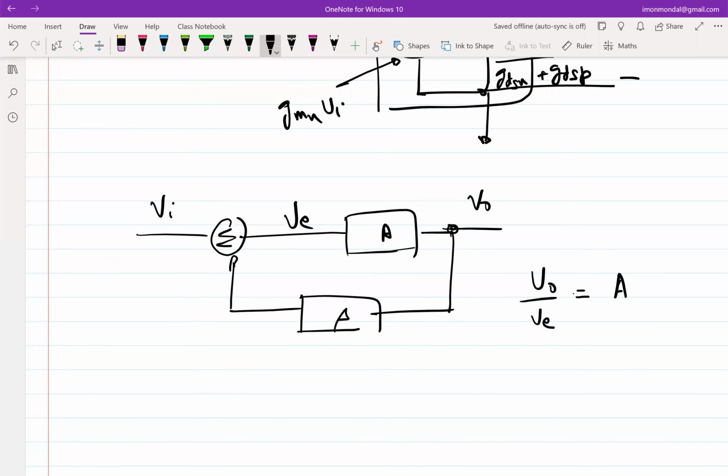So now what you are essentially saying is that in one case, the open loop, I'm applying the VI here, I'm breaking it and applying the VI here. In the closed loop, I have now changed my VI application, put it here. They are not identical cases. So if you have to figure out the gain, you have to keep the input application of the test input and your observation point the same. You cannot really move them around and say that it has changed. That essentially is the reason.